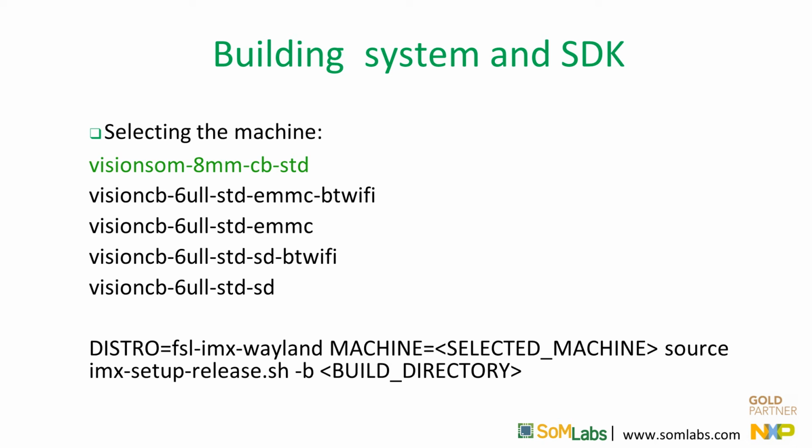In the next step, we define the machine for which the system will be built. In this case, VisionSOM8M SDK described in the meta-SOMLabs layer. The distribution, FSL I.MX Wayland, and the directory where the compilation will take place.